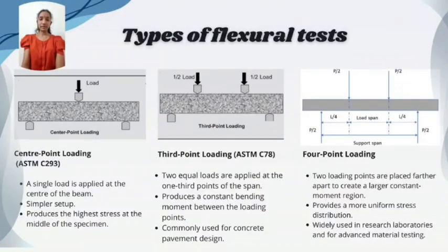Next is type of flexural test. First, center point loading. A single load is applied at the center of the beam. It is a simple setup and produces the highest stress at the middle of the specimen.